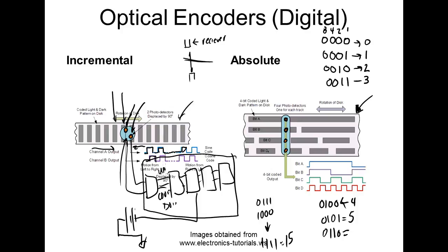So this is what the robots use over there. Every one of the robots has batteries in the base that hold this count while power is removed. So right now the ABB robot is turned off, but the counters still have their counts because what's in the base of the robot? Batteries. By the way, they call them absolute encoders, even though they're not, because they appear to be absolute encoders to the controller. But if you turn the controller off and you ever lose those batteries, what's going to happen? You lose the position. The robot is lost.